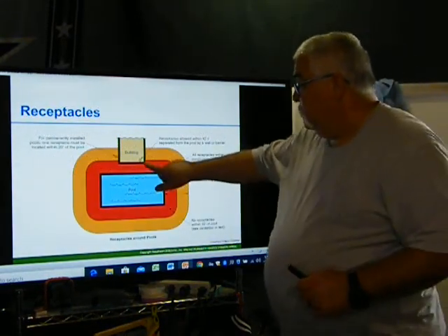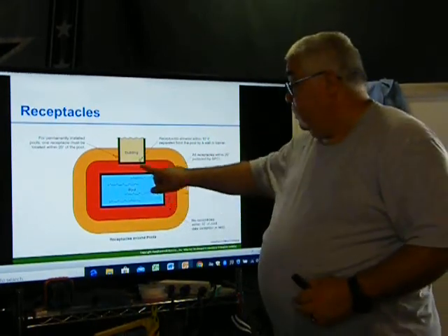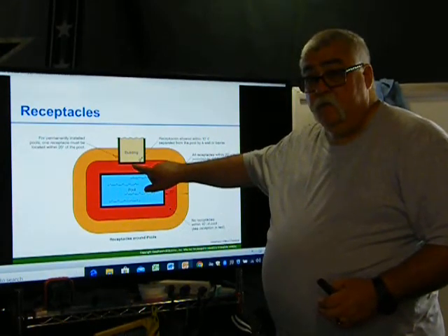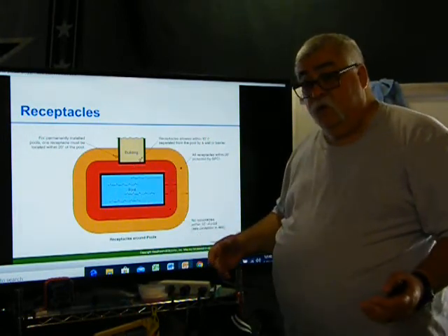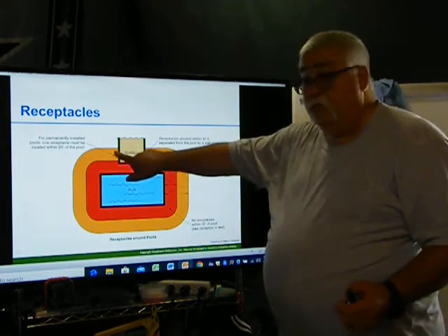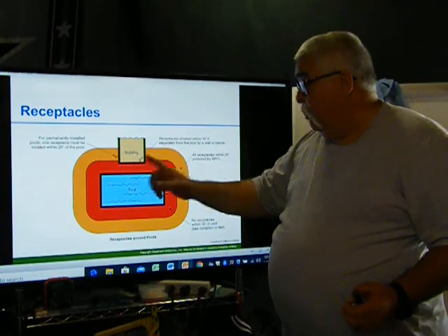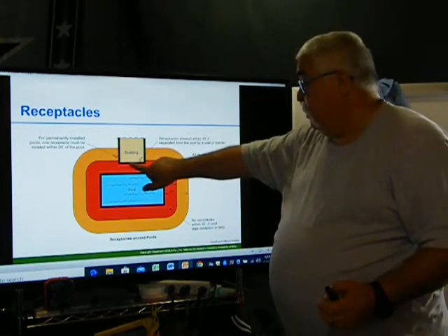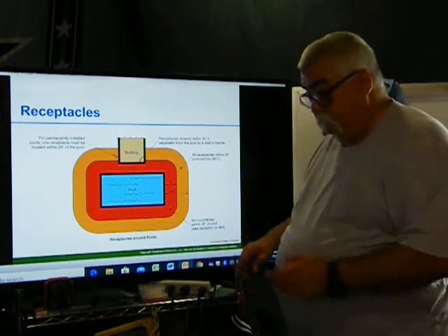You've got this building. Here's the 10-foot marks. Obviously, it's within 10 feet. And let's say you already have an existing light here. Okay, well, we're outside 5 feet, so we're okay. But if there's a receptacle there, I would take it off and have it moved somewhere else, outside the boundary. But if there was a light here in this building, then we're okay. It looks like it's more than 5 feet outside that wall.